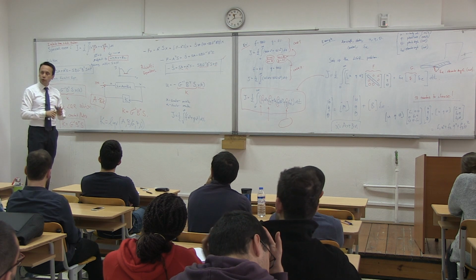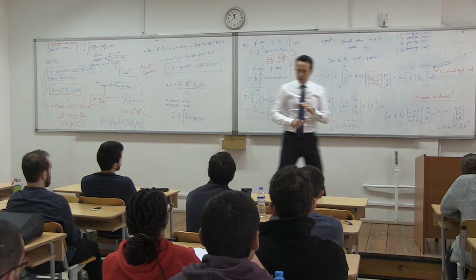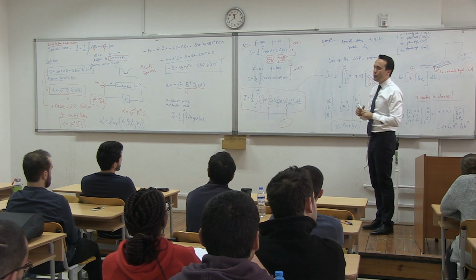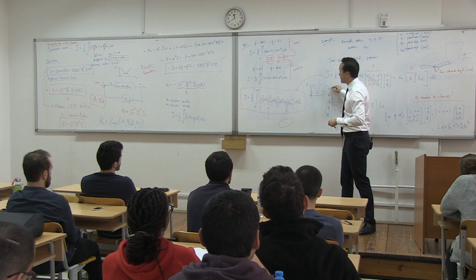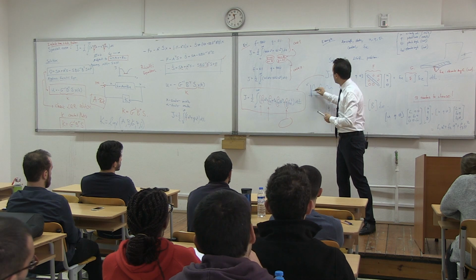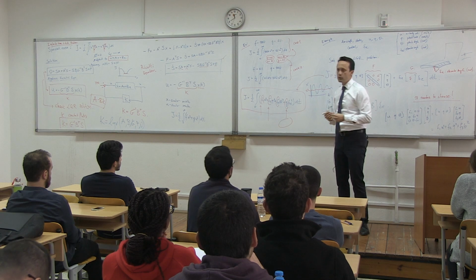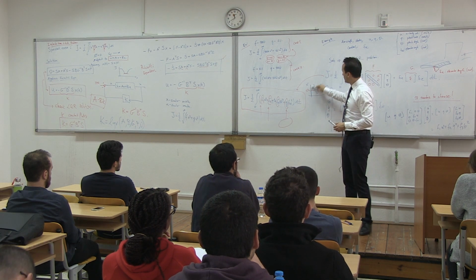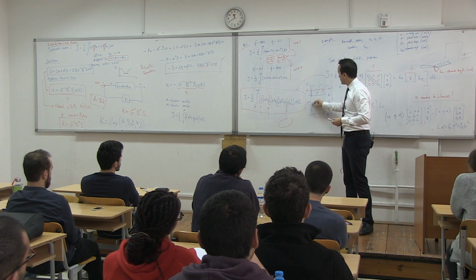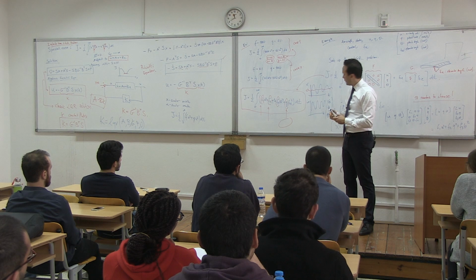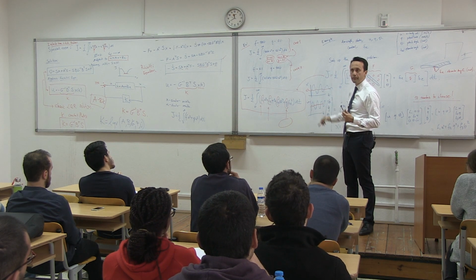We do an optimization of who's moving a lot. You understand when I say who's moving a lot, right? X in terms of time, I'm talking about this, is moving a lot compared to this, where this is 0, the equilibrium point. This is moving little, this is moving a lot. Same thing with U as a function of time. The control, the elevator is moving a lot, or the elevator is moving little. The best thing is to achieve both.